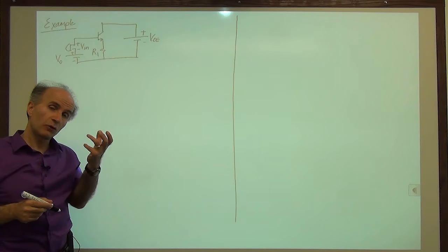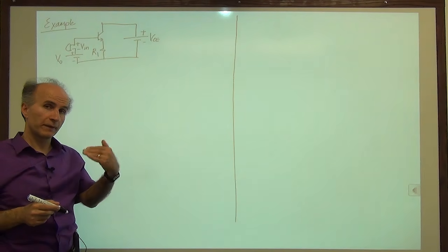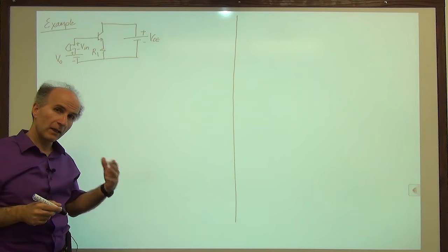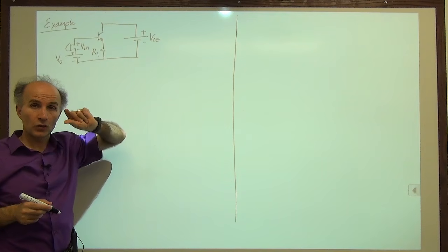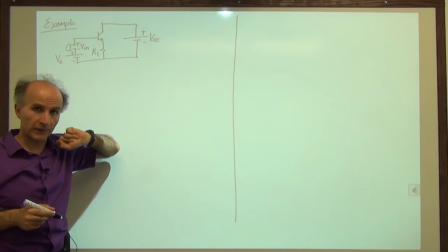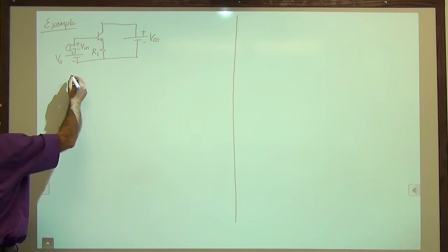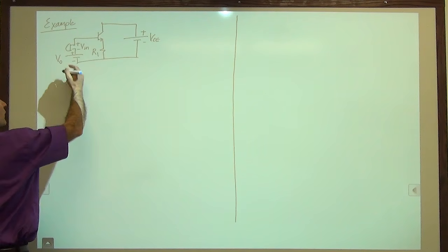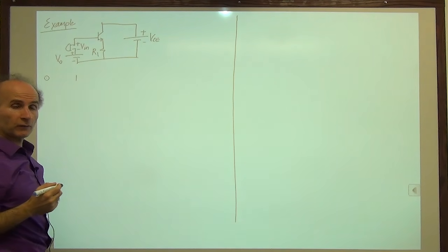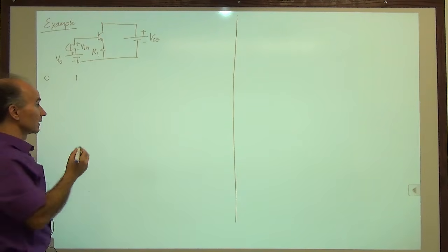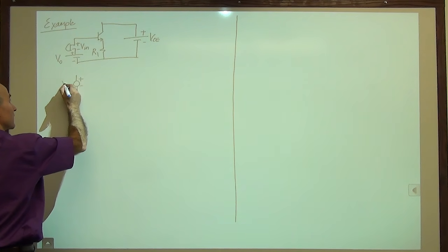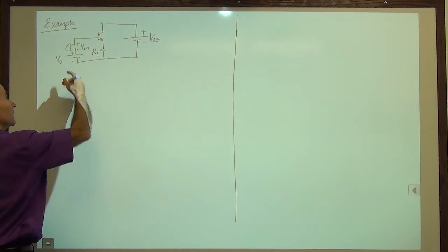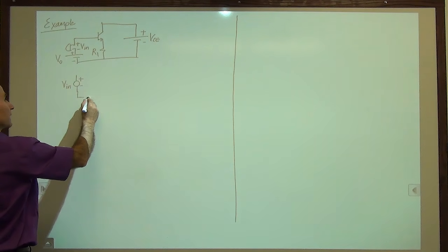So we replace the transistor itself with this small signal model. And then we also replace the constant voltages by short circuits, by 0 voltage sources. So this is what it looks like. For the microphone, we'll model the microphone by a voltage source. So the microphone remains because that's the signal. That's the perturbation. This battery goes away. It becomes a short circuit.